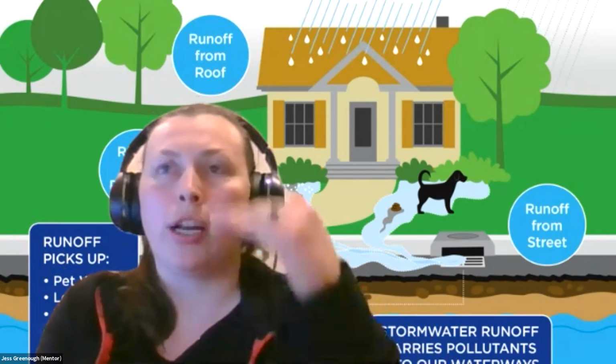Should that be our water quality feature, our detention feature, or should that be a tiny home or the community building? And then just start using that to help inform how we're going to be laying out our site. You know, where's the water line? If all of the water lines are on the south side of the property, we probably want to try to keep our buildings towards those so that we don't have to go all the way across everything else. So just observing what we have to work with out there and starting to use that to inform our site layout.